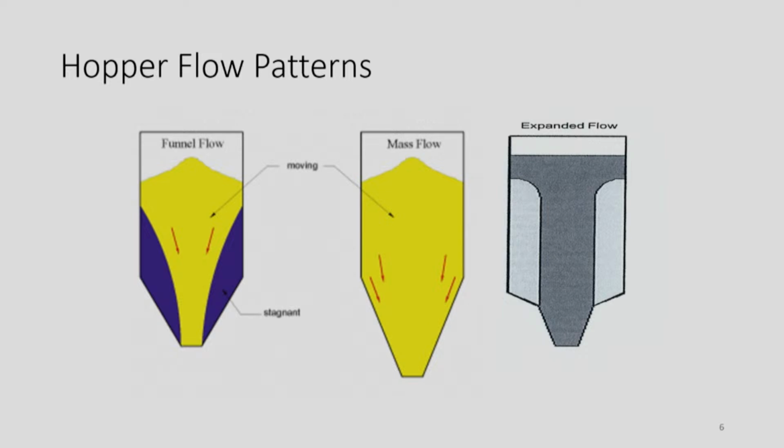But the total overall volume movement... Any other disadvantage? If powder is more cohesive, then it can choke the discharge. Yeah, definitely it can choke. There could be caking issues, but in general caking issues are high in funnel flow bins since the material is stagnant there. That's a good point.